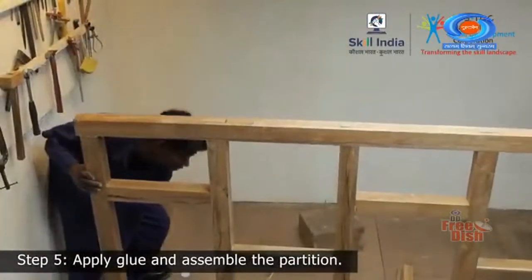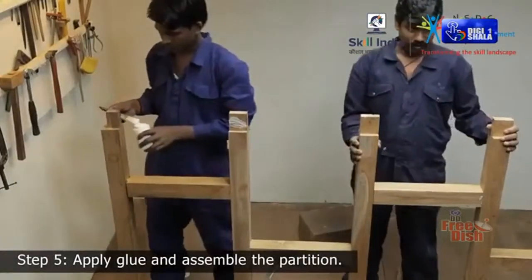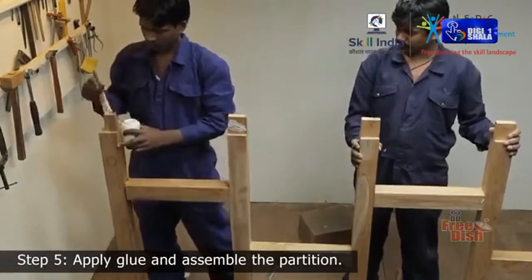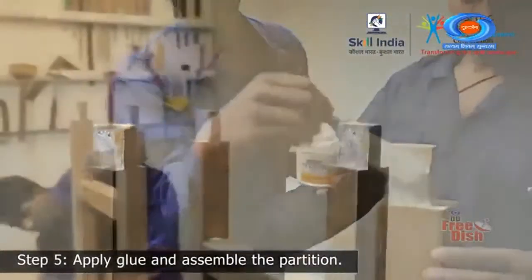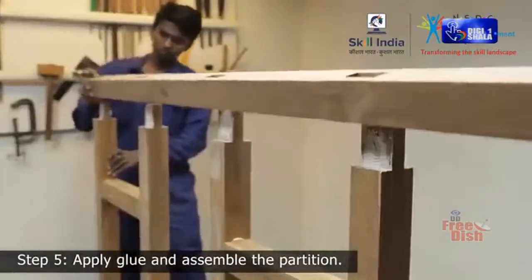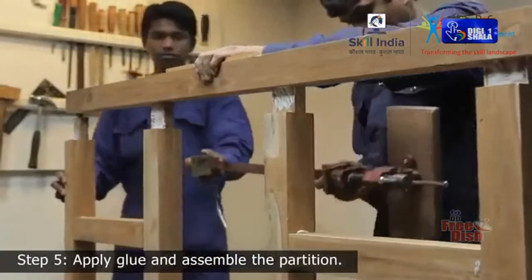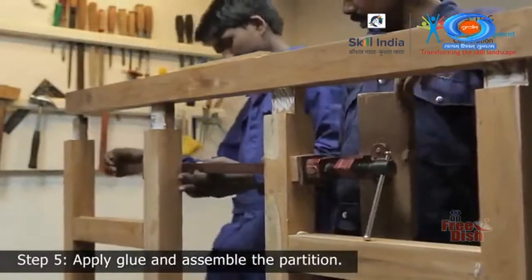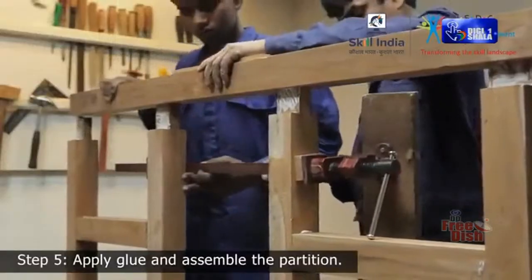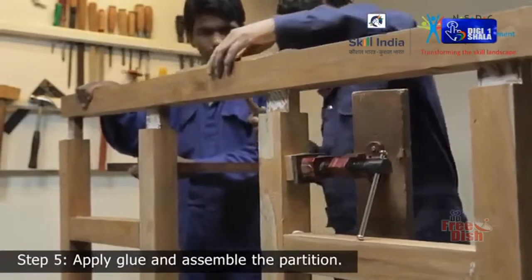Then once again rotate the frame and apply glue onto the tenon and place the top rail over it. Clamp the studs on the center with a T-bar clamp tightly so that the mortise and tenon members align properly with each other and tap lightly with a hammer till they fully set in.